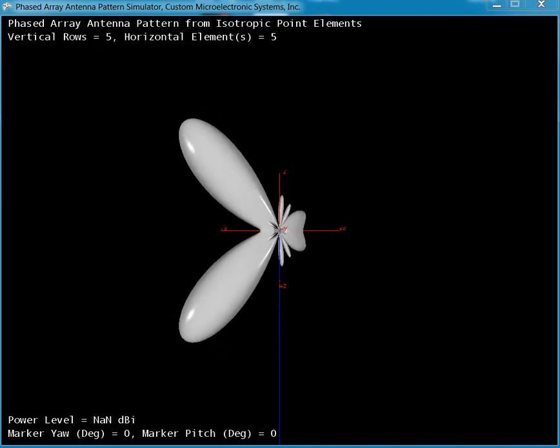See the beam starts to sort of fall apart there, I guess. I'll take that as a limit. And looks like we have a sweep angle of 42 degrees from center. Again, the gain is held at 14 dB, and using isotropic point sources, what's interesting is you do see the power of the swept beam doesn't change.